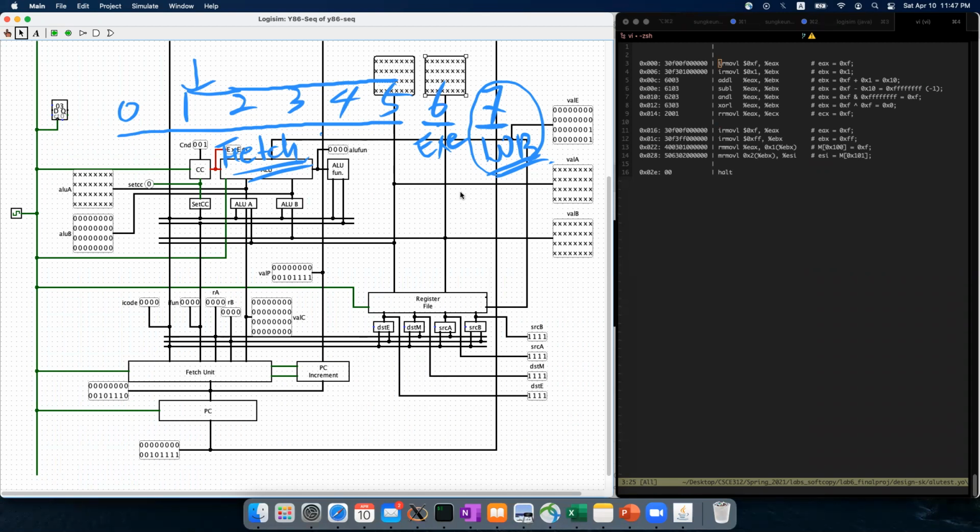What I'm saying is, if we put in another stage, which is a memory stage, we need to calculate this cycle timing differently. For example, in the write back stage, here we just assumed data is coming from the execution unit. But what if data comes from the memory?